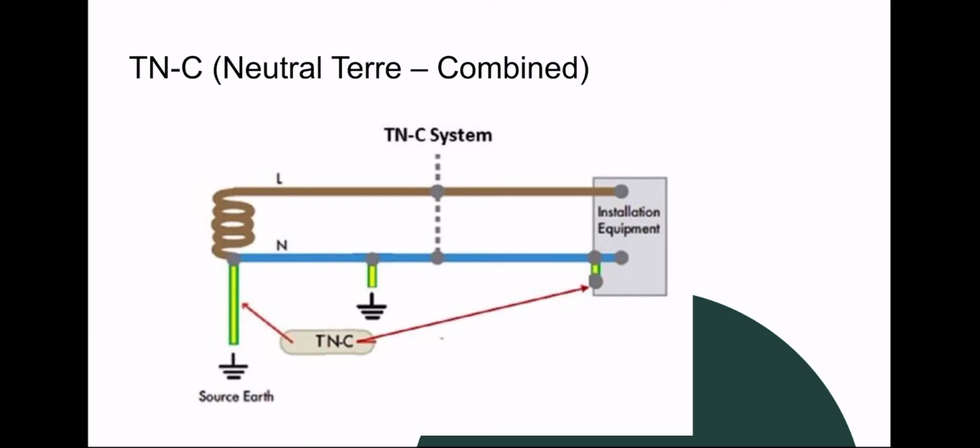This is because if a fault occurs, then at the same time the PEN conductor carries the phase unbalanced current and the third level harmonic current, and it multiplies. To reduce the impact on the equipment and the living things around the equipment, in the application of the TN-C system, the PEN conductor must be connected to a number of electrode rods for earthing on the installation.